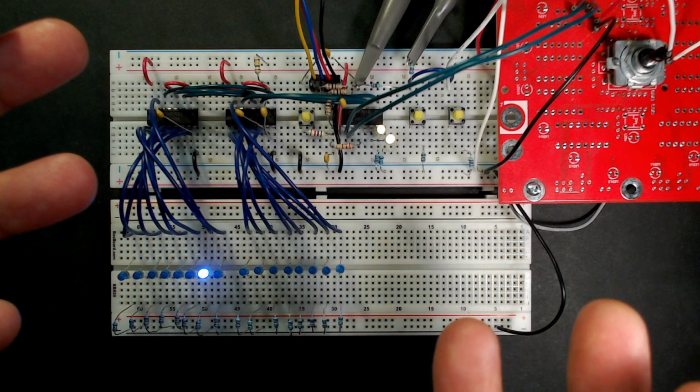Remember, we're working with breadboards over here, which are notorious for current leakage, particularly if you're working with very high resistance values like we are, 47 kilo ohms and 10 kilo ohms. That results in very low currents, which tend to find other ways to get to ground through these breadboards. So the voltages that we're reading are probably lower than they should be, which results in the errors. Now, I did do some testing, and I did confirm that we do have some voltage leakage out of these breadboards.